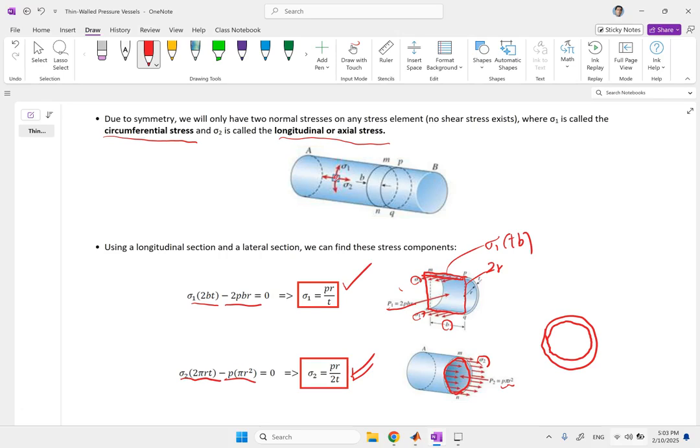Okay, so while your longitudinal stress for the cylindrical tank is the same as the stress for the spherical tank, in the circumferential direction you have 2 times bigger stress. This is the difference between these 2 types of tanks. Looking at these 2, you can clearly see that a spherical tank is better because the maximum stress in it is smaller, and it is the same in both directions, X and Y, but the cylindrical tank will get some bigger stress for the same radius and for the same thickness.